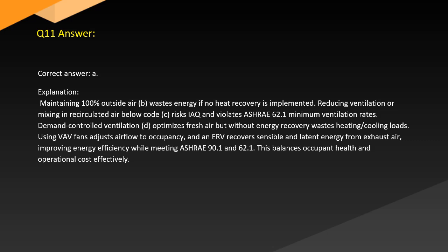Using VAV fans adjusts airflow to occupancy. An ERV recovers sensible and latent energy from exhaust air, improving energy efficiency while meeting ASHRAE 90.1 and 62.1. This balances occupant health and operational cost effectively.